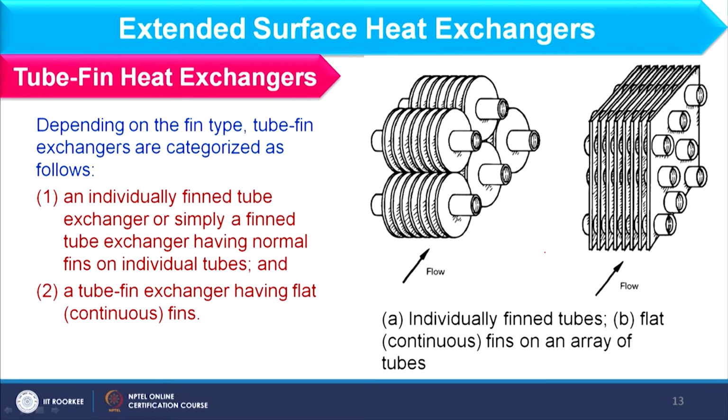Now if we focus on this schematic, here we have the tube fins. Okay, if I consider this image, here we have this tube, inside this tube fluid will move, and over this tube we have this disc type of fins. Okay, and because of the shape of these fins, it is called the tube fin, and it is attached over the tube. Okay, so it is like when you put CDs on a tube side by side, it is this type of structure, and this we call individually finned tubes.